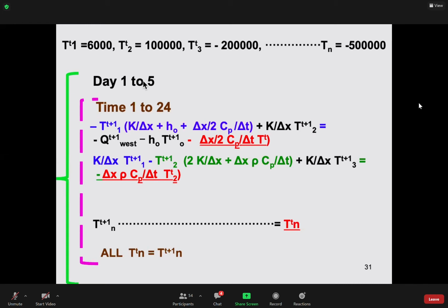Therefore you have to somehow be able to calculate, because when you calculate at number 1, at time equal 1, you come all the way to here and you find a value for T plus 1. It means you calculate the temperature at 1 hour. Then you go back, and it becomes 2. Therefore this value that you had here was the value at hour 1. So you have to keep all of them, replacing all of the new values in order. Therefore you end up with a 2-dimensional matrix that has 2 indexes, x position and time, T, N, M, okay? You have to put all the new values in the previous hours, and then you go back, okay? You have to do this all the way going back, okay?